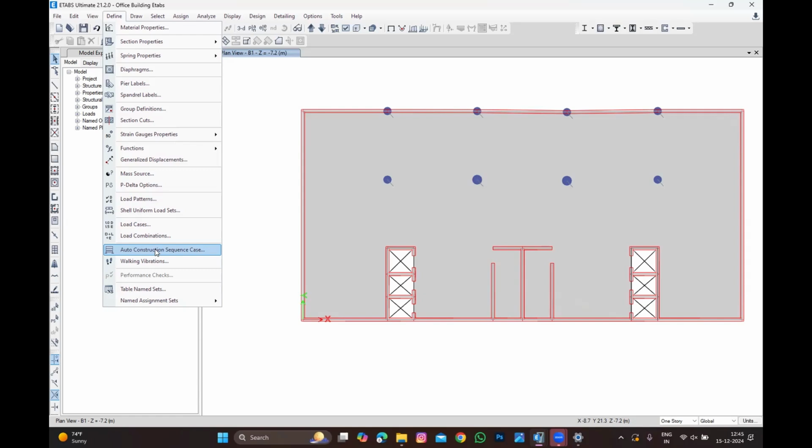Right? Okay. This is the fresh concrete, new concrete, 100%, which is the strength attained concrete. When you multiply the reduction factors, automatically strength will get reduced. If you use the modulus of elasticity as 4,700 root f'c for the fresh concrete, the deflection might be 10 millimeters. The moment you apply the reduction factors, the deflection might be 20 millimeters, because you reduce the strength, you reduce the grade of concrete. Automatically deflection will be higher.